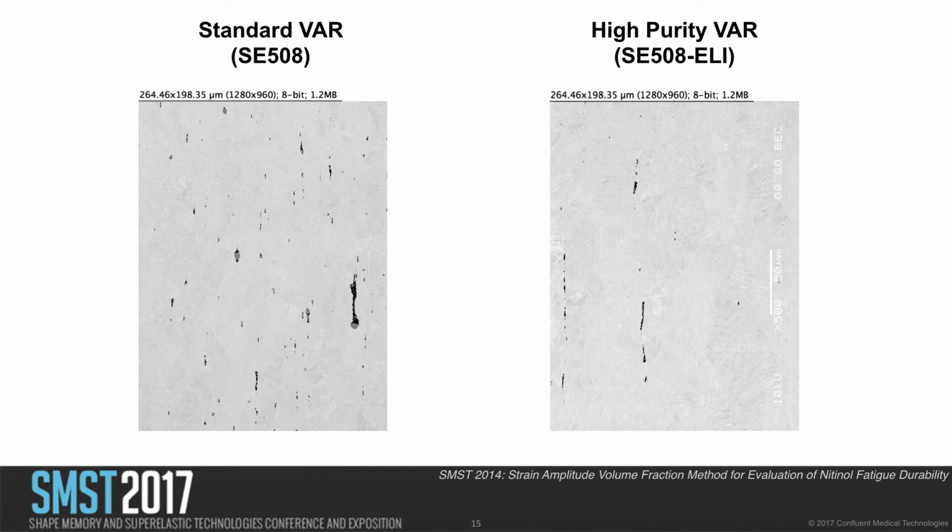And we find some way to get a contrast between the inclusions and voids and the matrix material, and we can then count up the dark spots and use that to somehow assess how much non-metallic inclusions or voids there are in the matrix, generally as an area percentage. That definitely gives us a lot of insight, but the methods to do this are not always straightforward or perfectly clear. There was a lot of discussion in the ASTM meeting here on site yesterday, debating different methods and possible ways to standardize this. Everyone has their own approach.